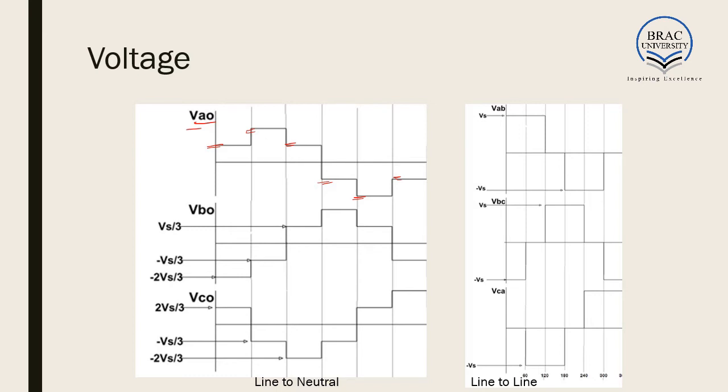So we have made all the calculations in our earlier slides, and we have plotted those calculations, and we get graphs similar to this. We can see that the graphs closely resemble sinusoids, but are not actually sinusoids. And again, we can see that here we have VAN, VBN, and VCN. All three have a similar shape, but they are shifted in terms of phase by 120 degree.